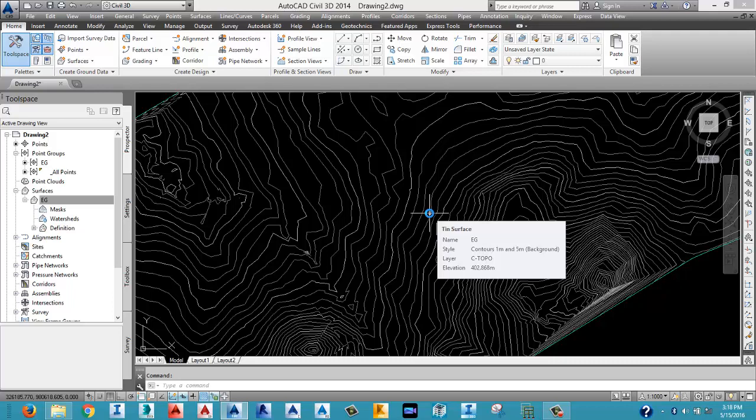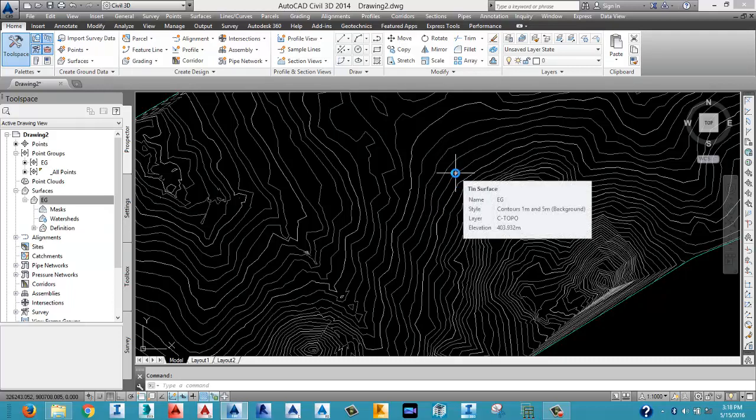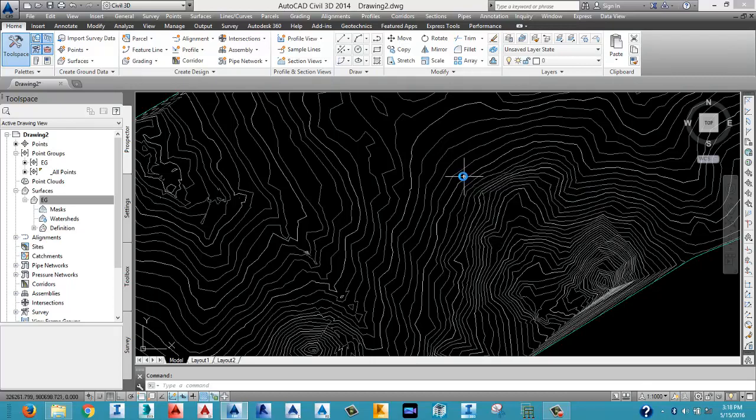So look at what I have on my screen here. This is a major contour, which is very thick and darker than this. This is the minor. You can have this major, and I go 1 2 3 4, that's another major. I go another 1 2 3 4, that's the major. So you have the minor at 1 meter, while the major occurs at the 5 meters.